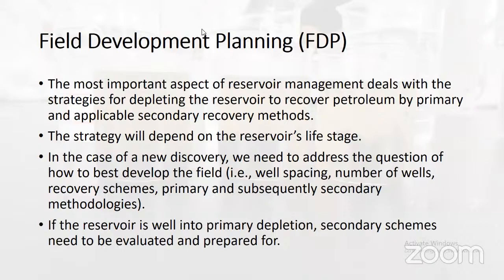The initial reservoir pressure is very far from the bubble point. So in that case, we can produce from this reservoir at the maximum capacity, because we don't have any problems related to gas production. But on the other side, you should study other problems like sand production, or any other production problems related to the wells and the reservoir properties.